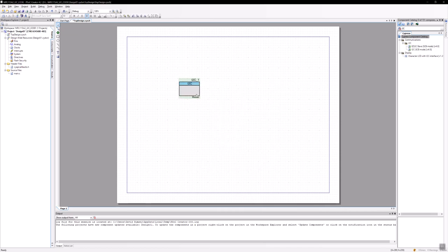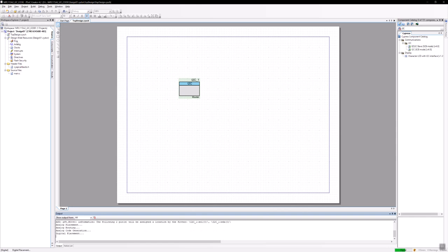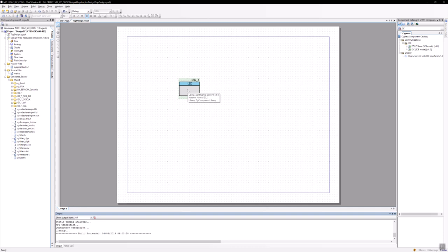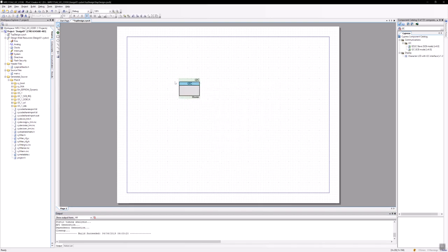All right, so again, we set it at master here, and then I'm just going to go ahead and generate my API. I didn't place my pins, I know, but the pins are automatically placed in the correct position for the PSoC. Actually, I want to change one thing here. I want to change this name to I2C.